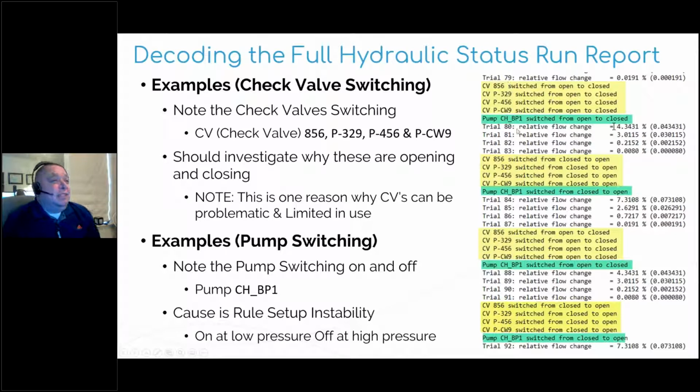And you can see in this one, it was sometimes waiting a few trials before it said, oh, I need to switch now. But if it's not converging because of this, it says, hey, this pressure-based control was just unstable, and so I just need to switch how that control is. The on could still be by pressure, because that's usually what you want. I want to make sure it comes on when I need it. But the off, I could switch to a rule base because that's delayed.